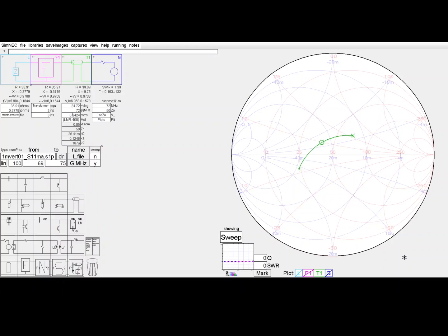So starting from the position where you see the kind of letter C, go back to that, kind of like a C shape, either on this side or perhaps on that side of the 50 ohm centre, looking at it through transmission line rotates the locus of the points. And if you look at a scan that you see with the curve rotated like that, you can form the view that it's quite probably the transformation, the results of looking through some length of transmission line.